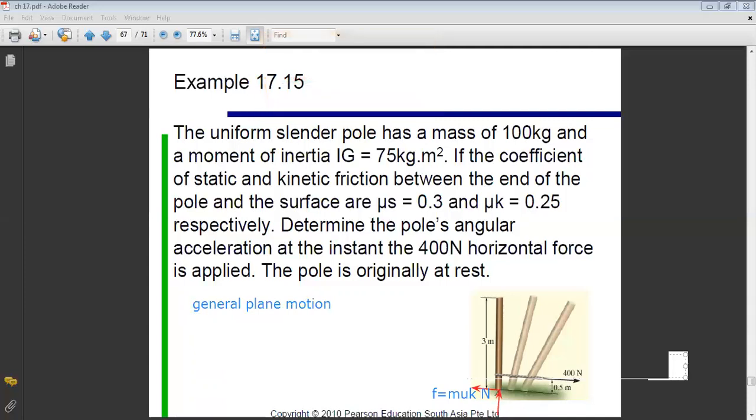Now, what are my other unknowns? For my center, for G, now G is not doing pure rotation about A, so I cannot write AG normal and AG tangential anymore. I don't know how AG is directed. This is why I will decompose it into two components, AGX and AGY, to be calculated. So I have two unknowns here for AG, which are AGX and AGY.